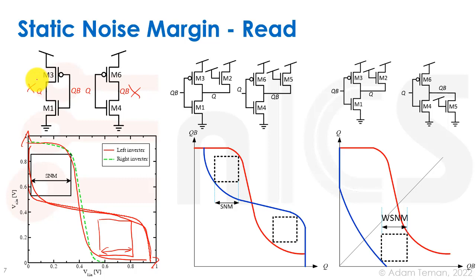On the other hand, when we enable the word lines and pre-charge to VDD, we get these 2 NMOS-type inverters as we saw before, and they're going to have some sort of a VOL over here.